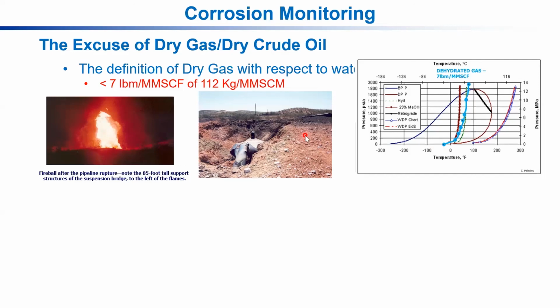But one thing that you have to keep in mind, this is dry gas because we dehydrated the gas in a dehydrating system. What is the reliability of the dehydration system? Is it 100%? Not necessarily. So 1% of unreliability is going to cause water into my pipeline that may get trapped, and then we have corrosion.